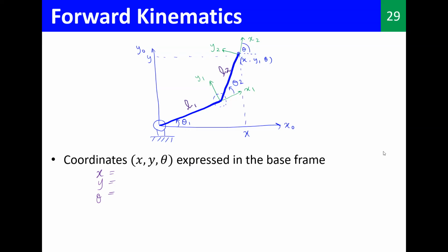It's better maybe if I ask. Let's ask Shaluta, are you there? So what's the answer? What is x? Yes, x is L1 cos theta 1 plus L2 cos(theta 1 plus theta 2). Right. And y? Yeah, y. Y is L1 sin theta 1.